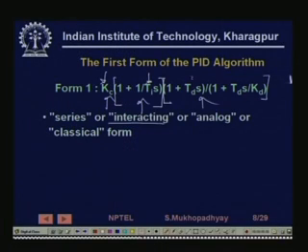So, you see that they interact; you cannot change them independently, unless you do it very carefully by actually solving equations. If you just change Ti, it is not just that the integral time is going to change, the derivative time will also change and the proportional gain will also change. So, the changes are interacting with one another, and that is why it is called an interacting controller.